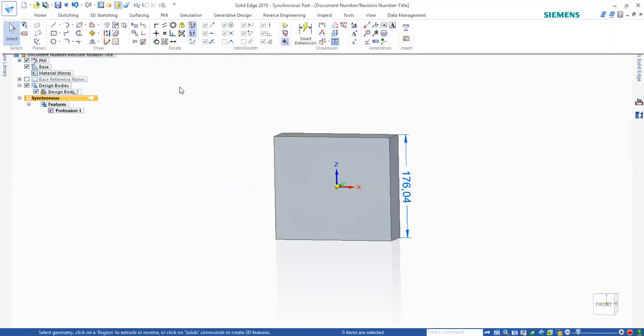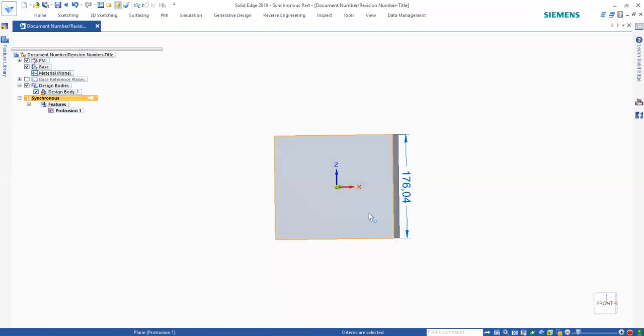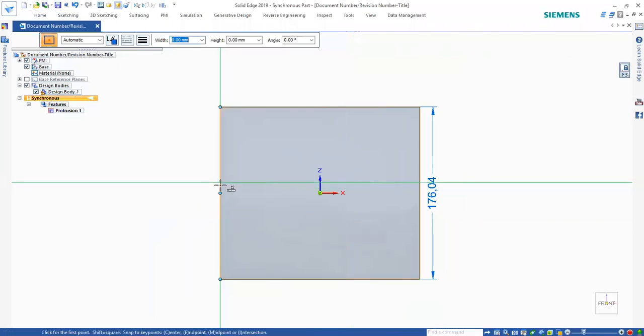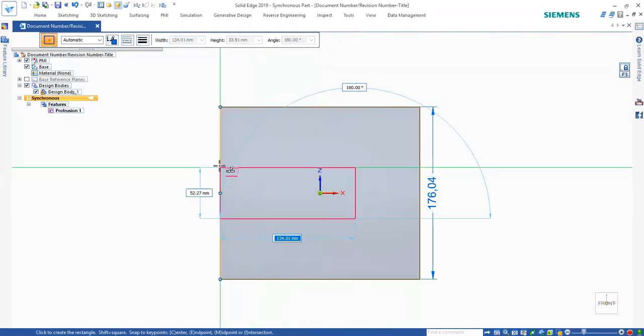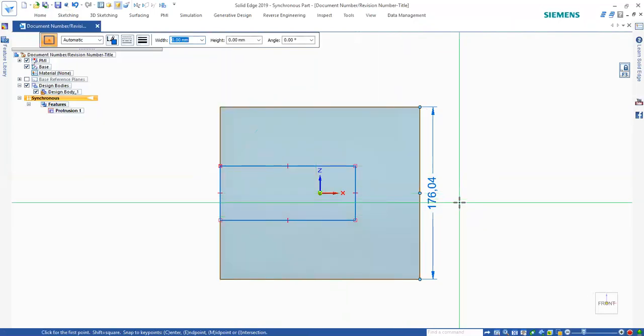And that's where we have the face relate commands. These are basically kind of similar to geometric relations at the 2D level, but in here you can do it on the 3D. So let's go ahead and draw on this. I'm gonna go ahead and draw on this face, so F3 to lock. Let's see, make one rectangle here. And make one here.